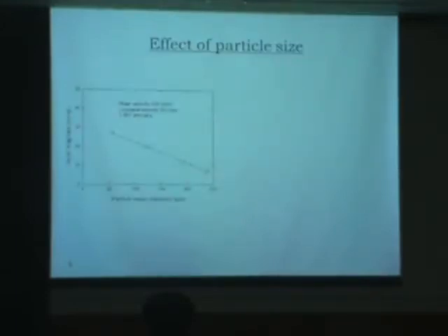Effect of particle size. When we keep the other parameters constant, riser velocity, loop seal velocity, and system pressure, at the same conditions, the solid flow rate decreases with the increase of particle size.